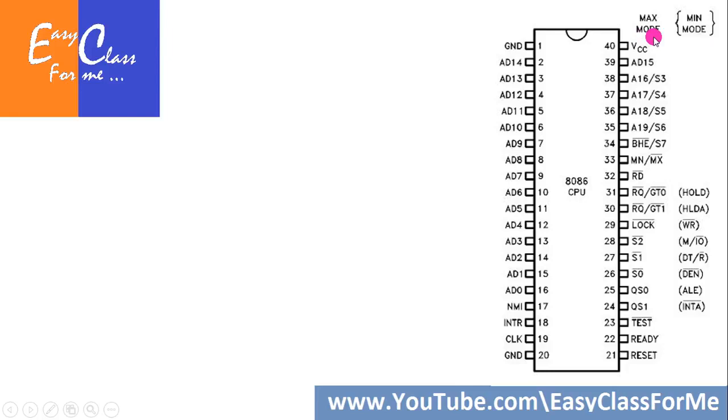So maximum mode means there will be a parallel operation between different processors, and different processors will be performing different subtasks of a very big task. So in that case we call it as a maximum mode, and depending upon that you can see that inside small brackets whatever we have written is applicable for the minimum mode, and outside these small brackets whatever has been written is for the maximum mode. So these are the pins for which this bracket is given here. These are the pins which can be used either for maximum mode or for minimum mode. Rest all pins can be used in both of the modes.